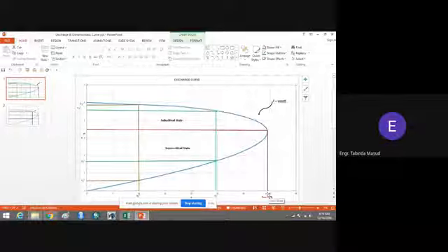Okay, so from this discharge curve we have come to know that there is only this point where we have the single depth of the flow, and that single depth of the flow is known as the critical depth of the flow, except this value for the maximum unit discharge. For all other discharges, you will always get two depths of the flow, which are known as the alternate depths of the flow. Remember that this discharge curve is on the basis of the constant specific energy.